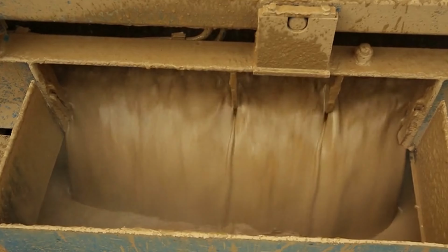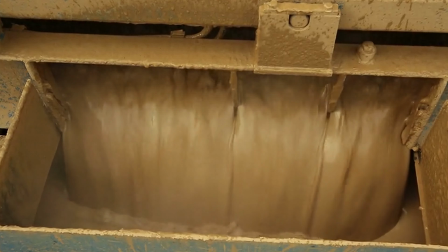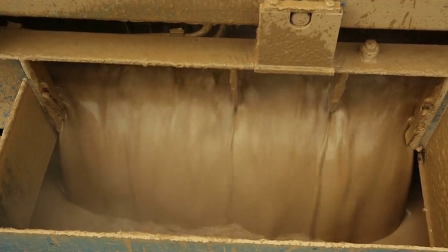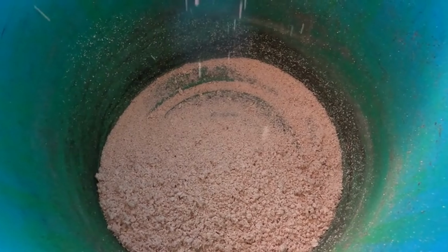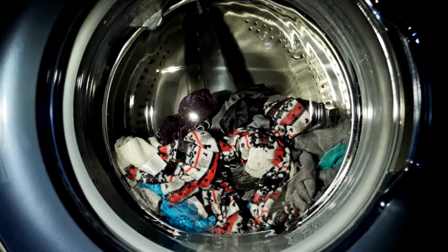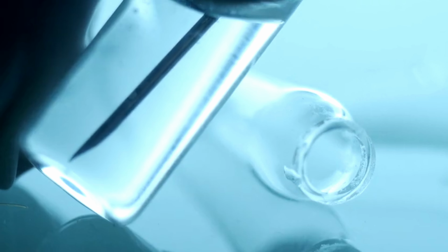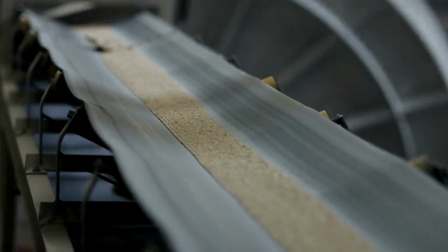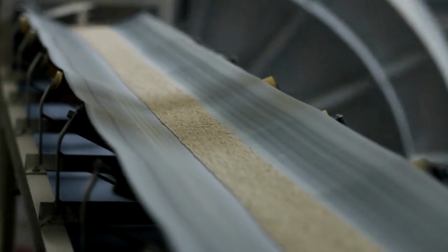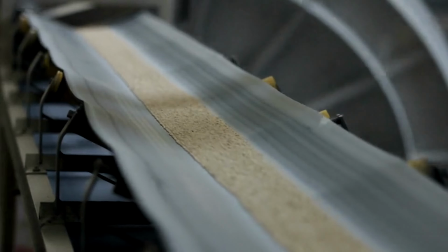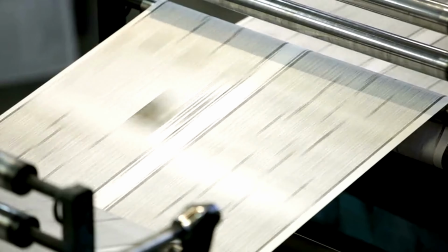After pulping, the raw pulp contains fibers, water, and residual impurities that need to be removed. Screening. Large particles like knots and dirt are filtered out. Washing. Water is used to remove residual chemicals and lignin. Refining, beating. The fibers are beaten to improve bonding strength and paper quality. Bleaching. For white paper production. If white or bright paper is needed, the pulp undergoes bleaching.